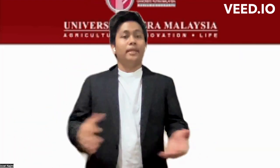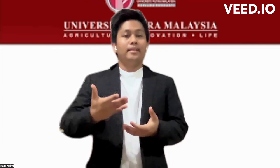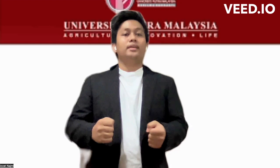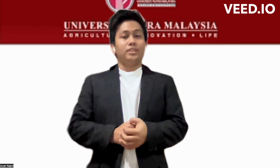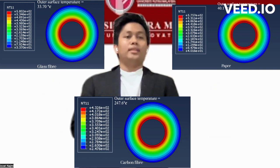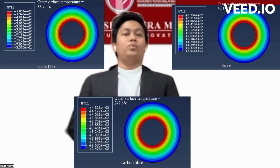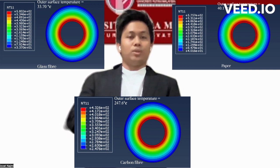Second, input the material properties, meshing, initialization, and post-processing, and finally visualization and plots. For the result, the initial temperature set, which is the average combustion temperature inside the rocket motor, is 600 degrees Celsius. As a result, we can see from this figure that all the propellant grain insulators have been simulated and the visualization has been made, representing the temperature contour.